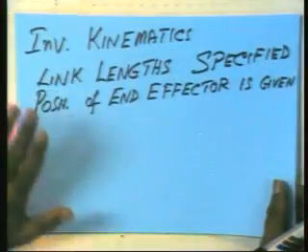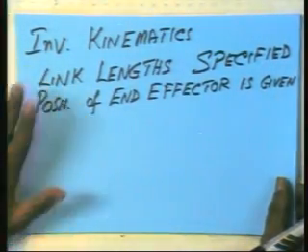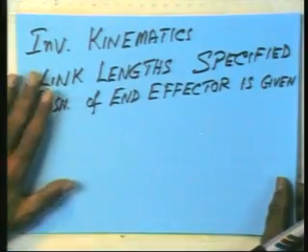That is what I would like to request you to do. Okay. So now we have seen the planar 5-bar closed chain as well as the 6-bar closed chain. The 5-bar closed chain allows you to position the object. The 6-bar allows you not only to position but also orient, because it has 3 degrees of freedom.